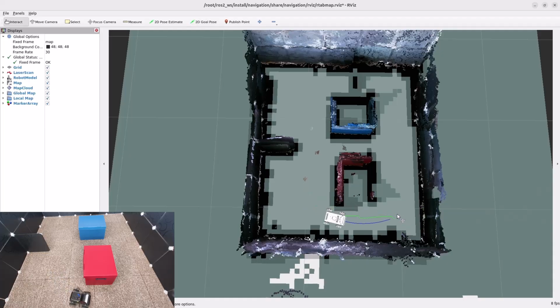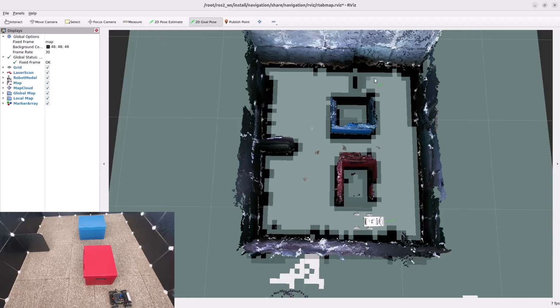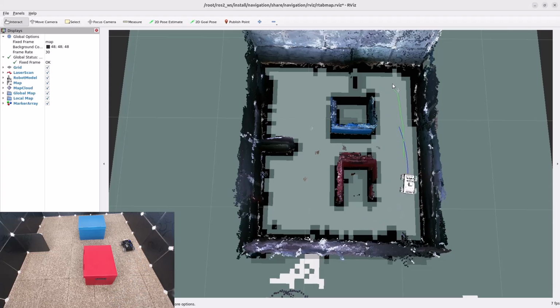The dark blue line is the practical solution. The path planning algorithm calculates this route considering all known obstacles from the 3D map, safety margins around obstacles, the robot's physical dimensions, and dynamic constraints like turning radius. This visual representation helps you understand both what the ideal goal is and how the robot will actually achieve it.